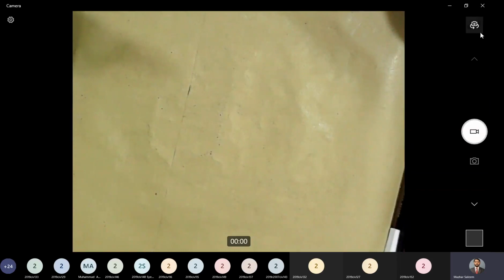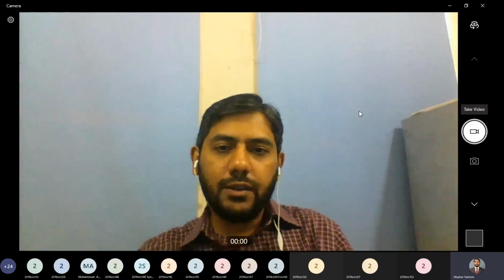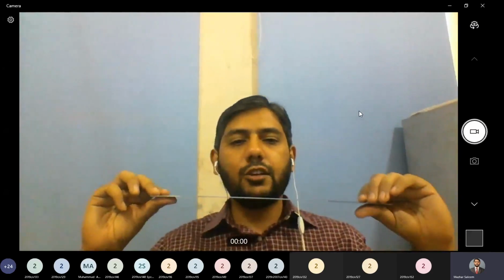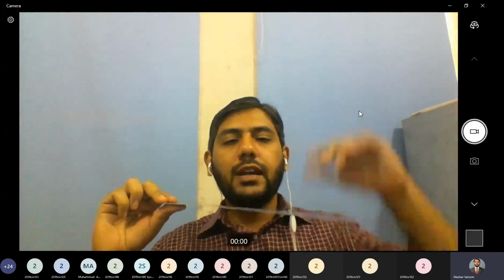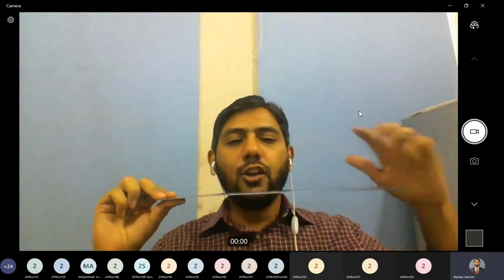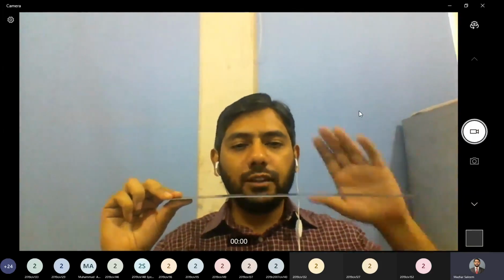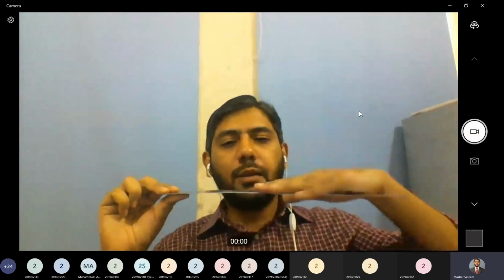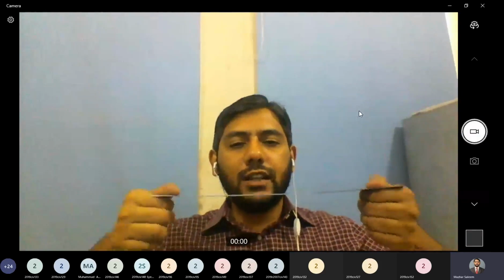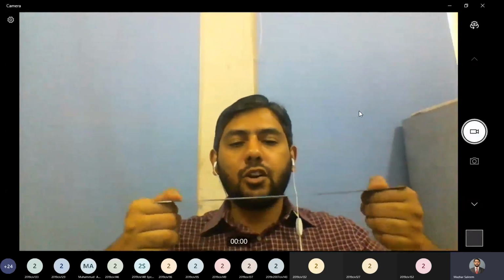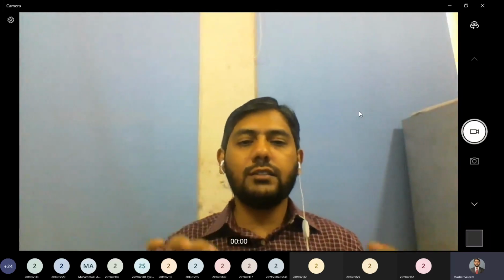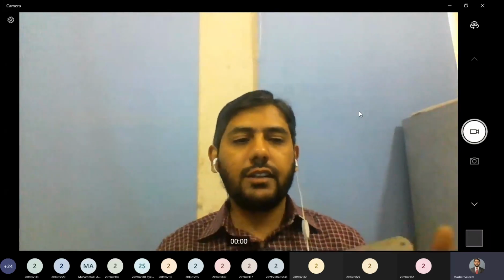So what we do for that, let me turn on the camera. Supposedly we have this beam and we decide that we want to perform a load test for this beam and we are going to actually load this beam. So before starting putting the load on this member, we install a deflection gauge at the bottom and then we apply load, and whatever deflection takes place afterwards is recorded by the deflection gauge. So we do not install these deflection gauges like